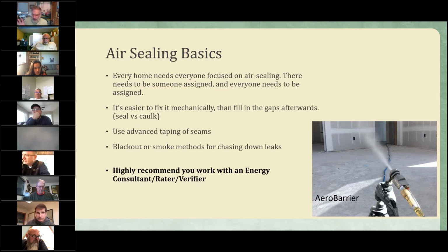I want to mention really quickly, there is a product called Aero Barrier that is a fantastic product. Basically they spray a silicon powder sealant that floats through the air. At the same time, there's a blower door hooked up, blowing air in, and it basically flies around the house, finds any type of gap in anything, and fills it up. It can sometimes take several hours, but you can basically go into a home and say, what ACH do you want? They'll just keep this thing running until it gets down to 0.2 ACH.